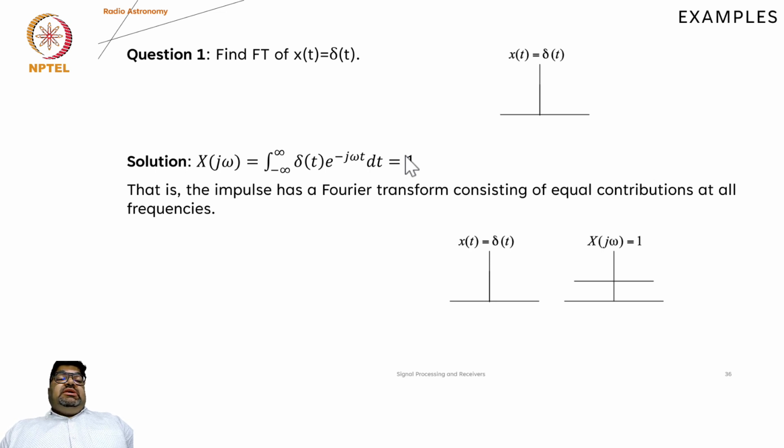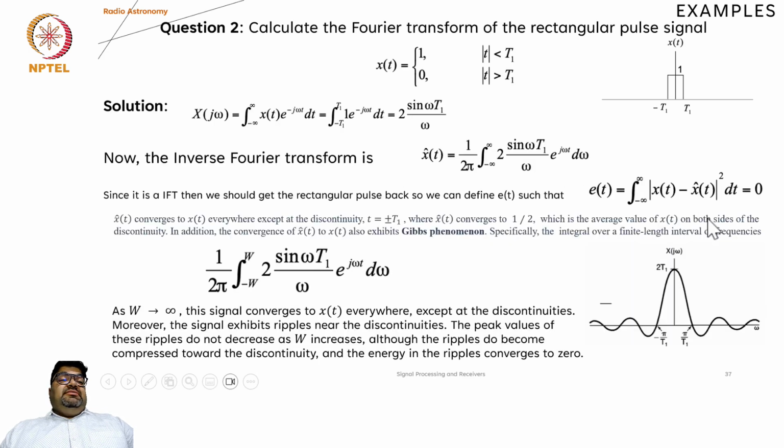It's a very powerful transform, because what it says is an impulse in one domain is a constant broadband DC signal in the other domain. We will definitely be using this in several derivations, but also we'll be coming back to this particularly in terms of interference. When we come to the radio frequency interference signal, we will come back to this particular property and refer to this property quite often.